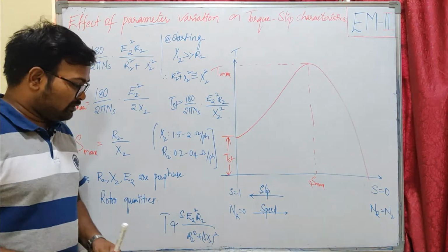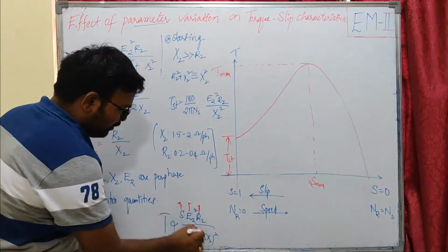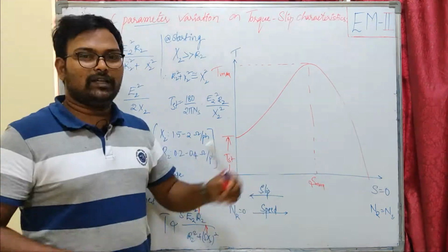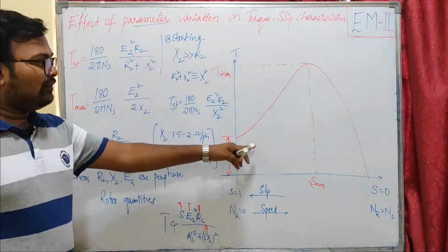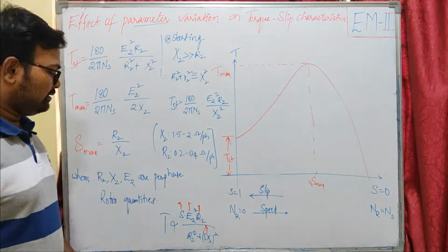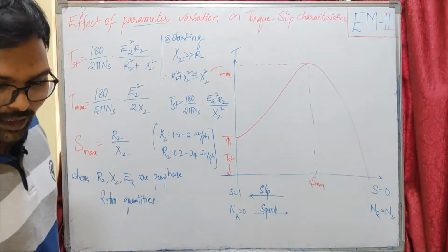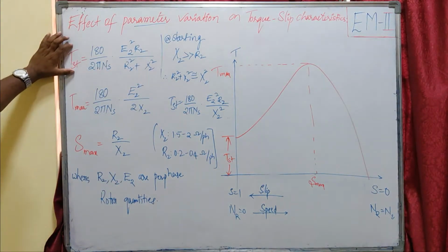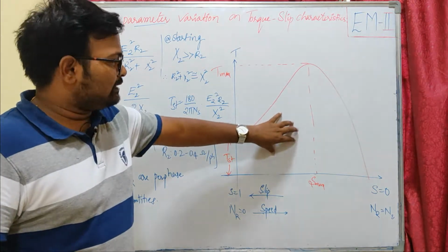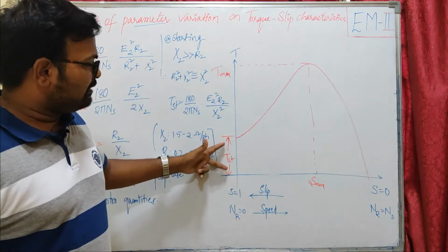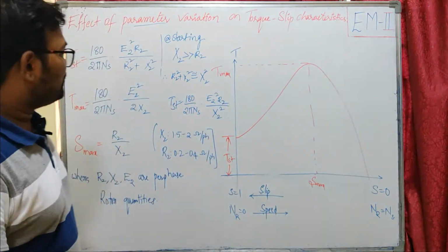I have to change each and every parameter and see how the torque slip characteristics of our 3-phase induction motor are changing. For that, I am considering the starting torque, the maximum torque and the slip at maximum torque. Let us see.